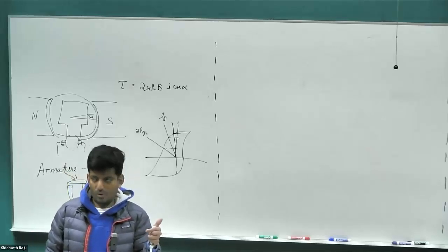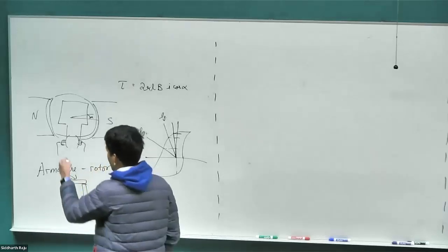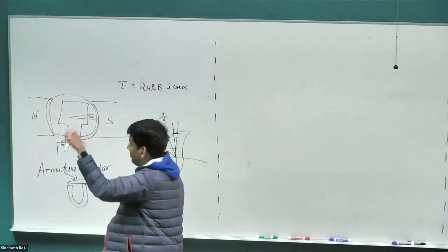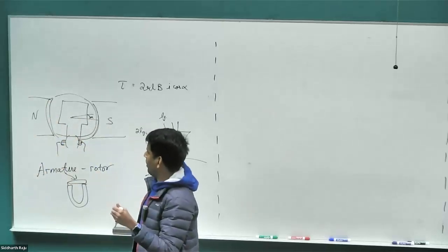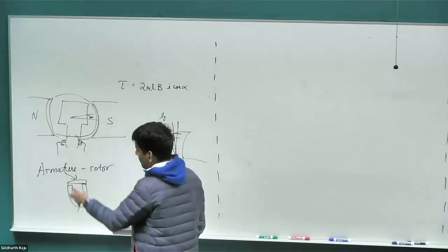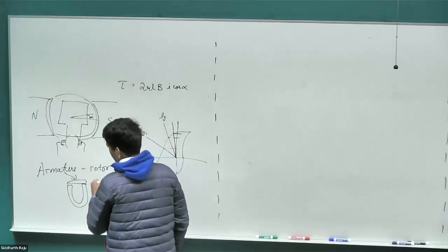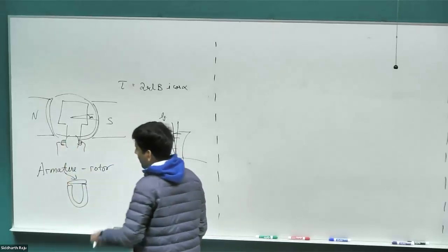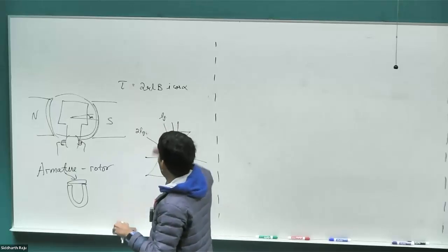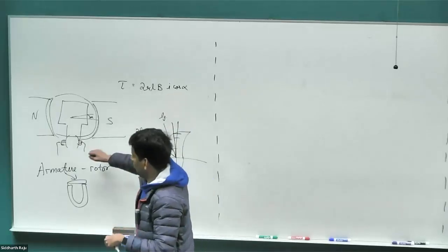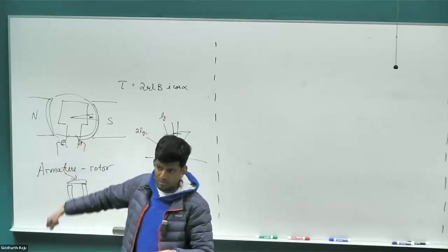That's the one bigger problem we have, because all of these are copper wire, but they are still very long wires, so they will have a significant amount of resistance. And then we have these brushes, which have quite a bit of resistance, and then the wires that come out. All of these resistances add up. That means if the current is very high, the total power loss in your motor will be very high and efficiency will come down.